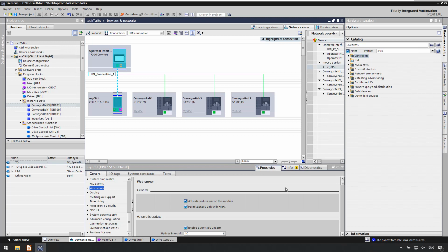If you look at our previous tech talks, I'm pretty sure that we already talked about this. Well, it was actually me who talked about this when I was talking about the future communication protocols. And then I showed a demo on how you can write another program to connect and send JSON RPC commands to extract some data from your PLC using this new web interface. But it needs an HTTPS connection. So it can't be HTTP, it needs TLS encryption for security of the data transfer. So that's all good. That's all ready for us.